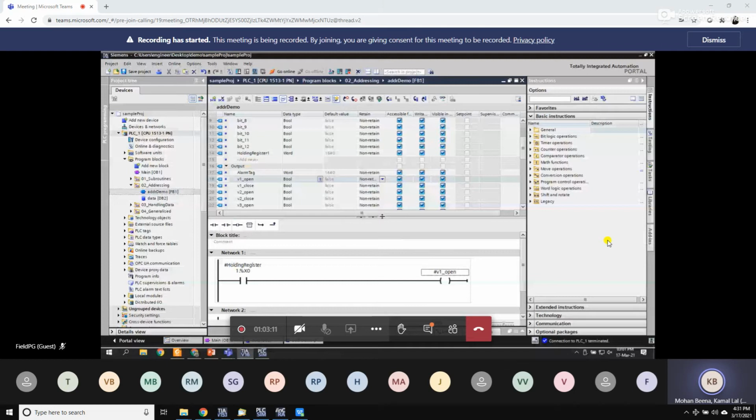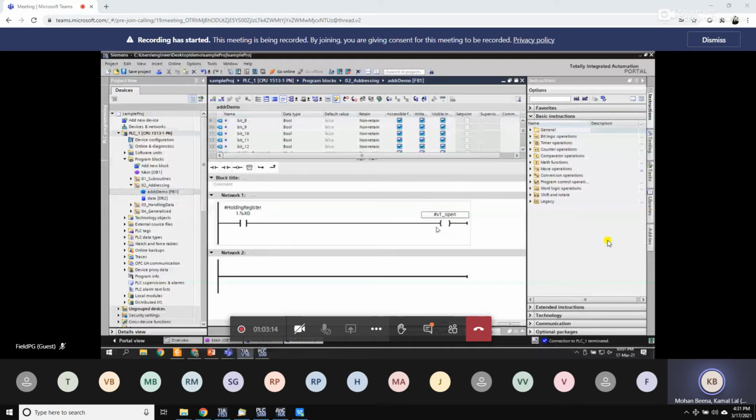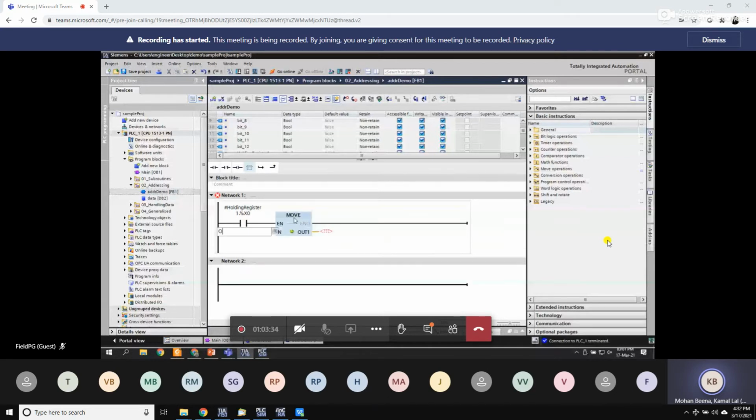If only it was just as simple as this, it would have been okay for you. But in most cases, maybe you want this access acting as an interlock for starting some pump. So when the valve is open, then you want the pump to be on. So you will be giving some on command to some pump in this case. But tomorrow, when you come and look at this particular program and see this holding register %x0, you don't understand what that is, right? So with the slicing access, we don't have the full efficiency of having symbolic names.